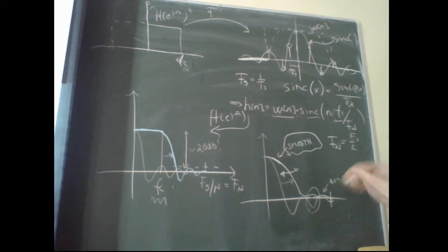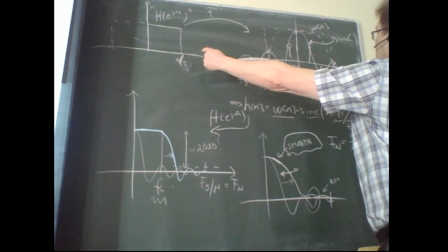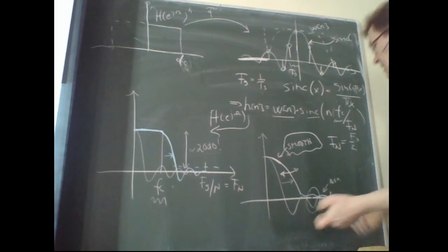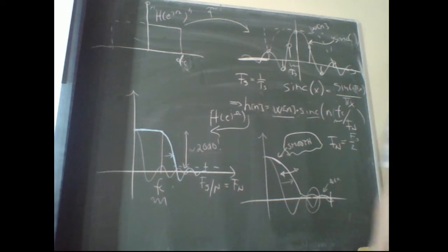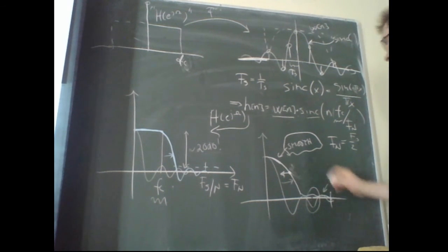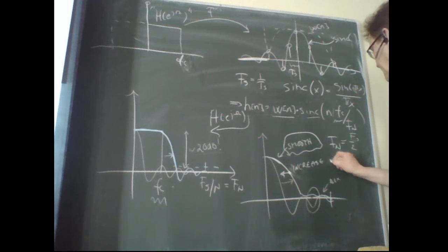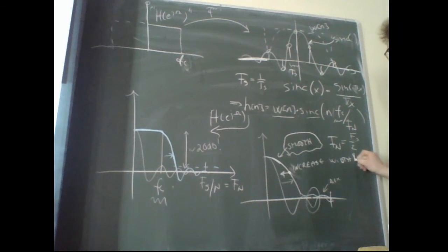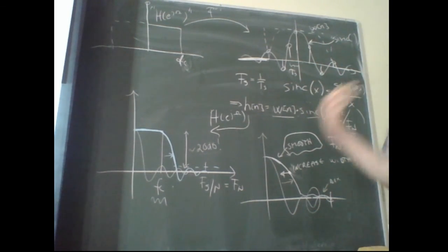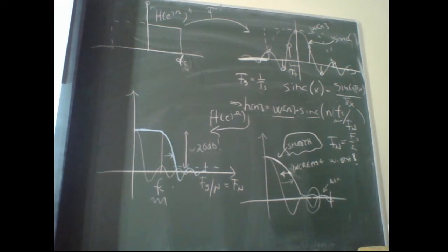So it means multiplication in time, meaning a wider sample of the sinc, would decrease the transition bandwidth. So to get a better transition bandwidth, increase the width. No magic there. Good. So that's how the window method for low-pass filter design would look.